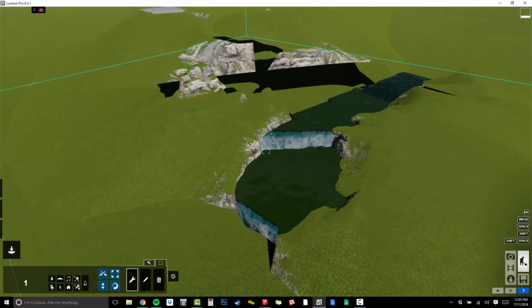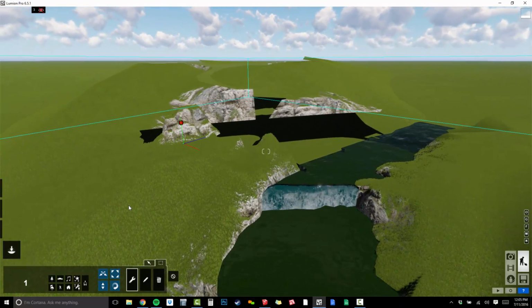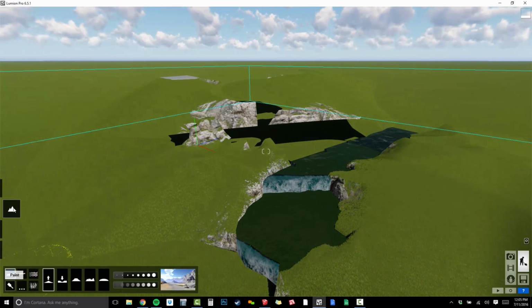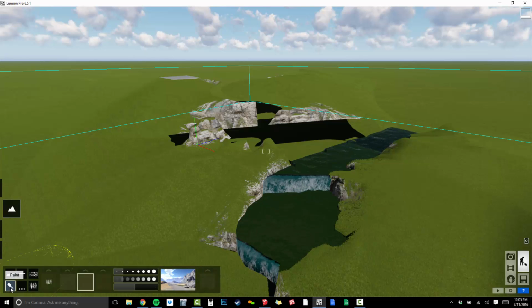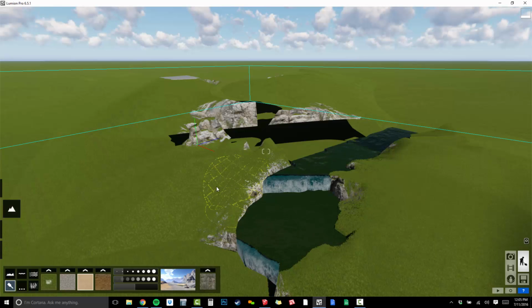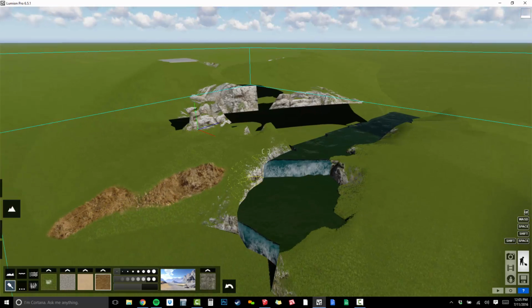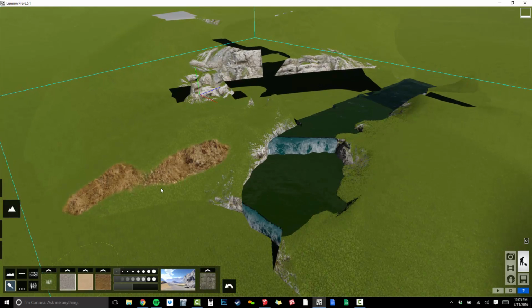All right, so now what that means is that this site, all of this, is now marked as terrain, which allows me to go to my landscape tab, and on the paint tool, I can now go in here and paint a little bit. We can dial our brush size to be smaller, our speed a little bit bigger, and then I can just paint that ground on there. You could go in here and start to craft that site.